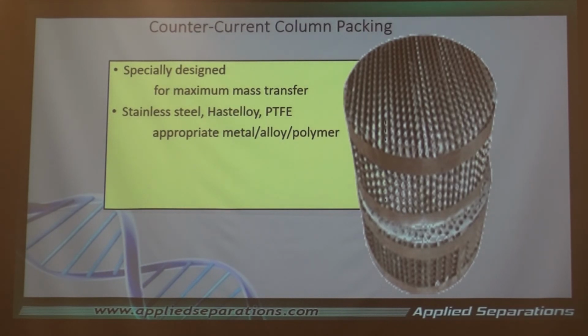There's an example of some of the inert materials. Sometimes they're just various glass beads or steel balls. They can be any number of things. You're just looking to disrupt the flow to get the maximum amount of interaction between the liquids. That's the same sort of thing when you're doing this with a separatory funnel. How long are you going to shake it to get the maximum amount of transfer of the solute into the other solution? You're doing the same thing here.